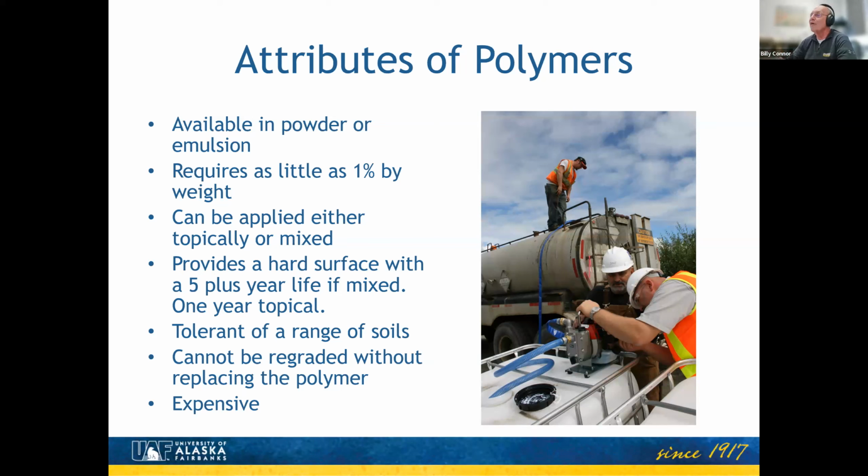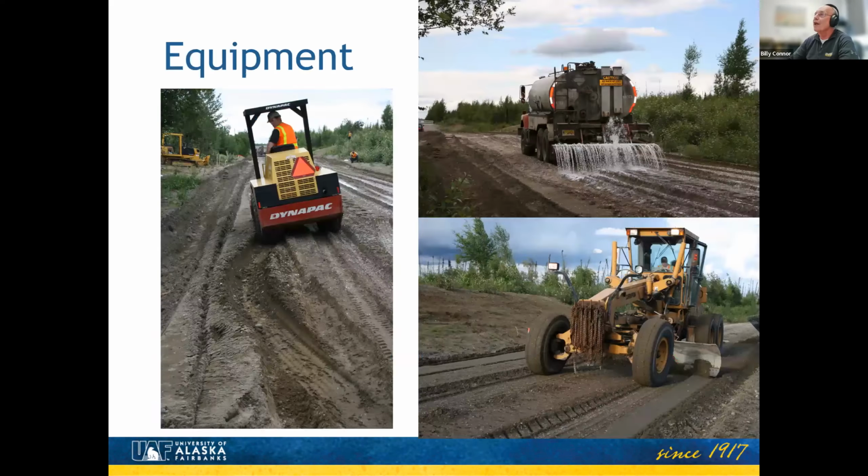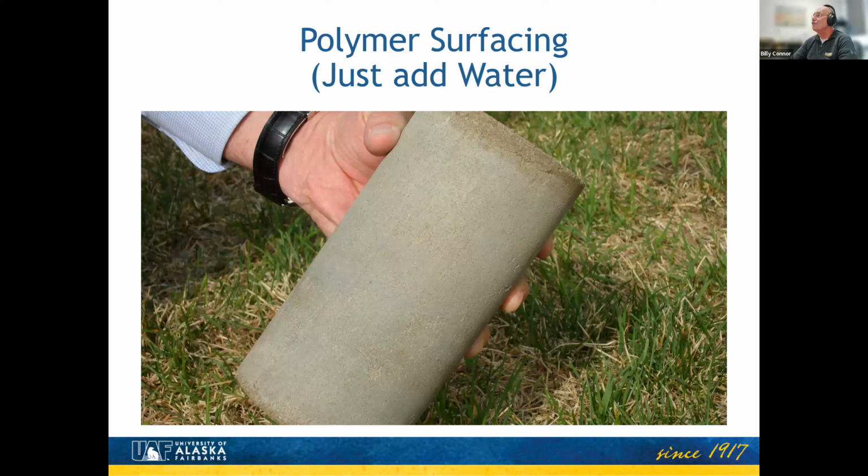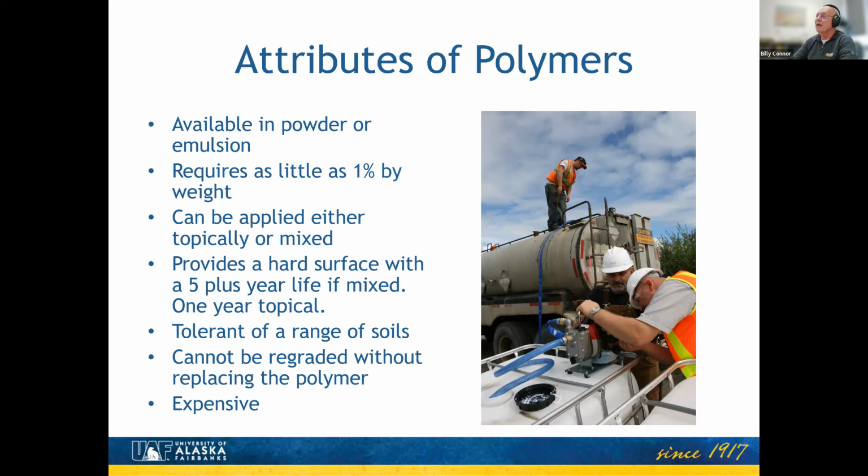The polymers are very tolerant to a large range of soils, and that partially answers your question. Polymers are a good choice for sands. In fact, the photo that I showed you here is a sand from Horseshoe Lake that we mixed, and this is what it ended up looking like after a couple of weeks of sitting on the shelf. So we can do that. We can use it on coarse gravels, sandy gravels.